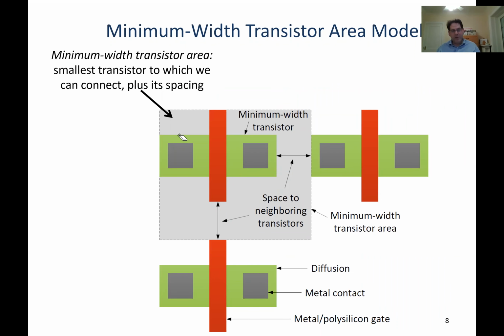One of the things we're going to have to work out is how we build all that stuff out of transistors. The other thing is that I'm not actually going to sit there and do layouts of everything. We're going to estimate from transistor-level schematics how much area this is going to take on the chip. That's commonly done in FPGA architecture research, because laying everything out would take a really long time. So we really just want a metric that correlates pretty well with final layout area.